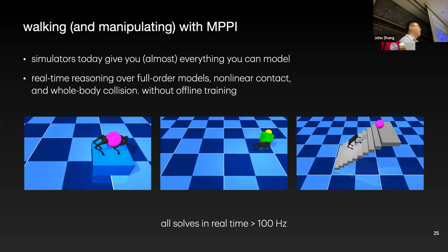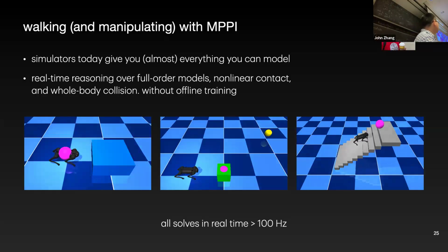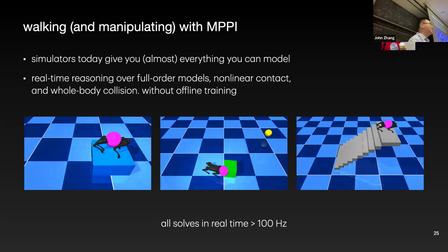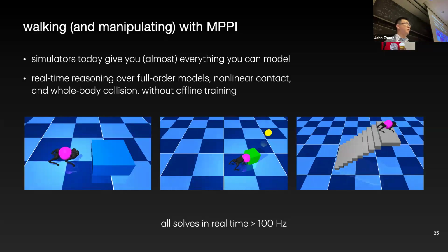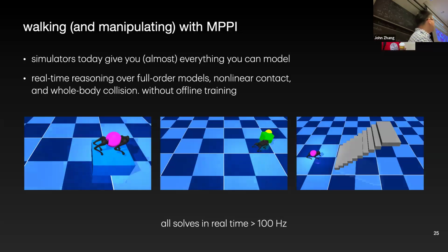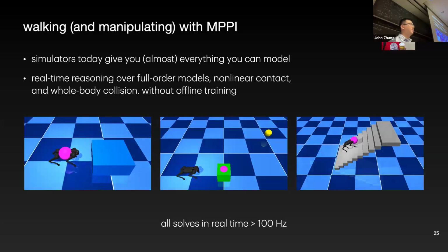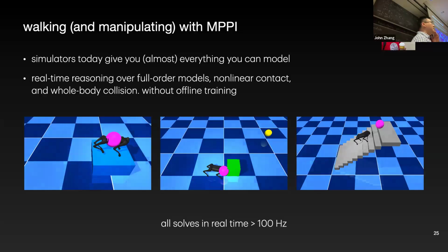Surprisingly not. Okay. So basically what we're doing here, we have a reference gait. The reward is to track some reference gait based on the Raibert heuristic, basically the standard stuff. And the rest is just MPPI coming up with the gait sequence to climb up on that box.